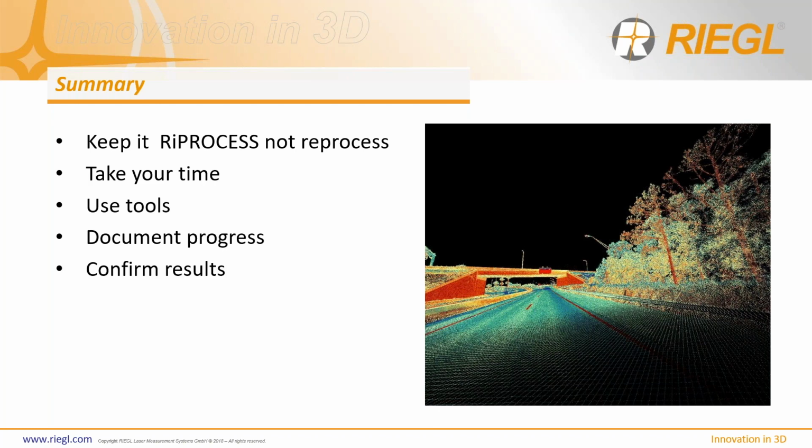Confirm your results. Check the control points. Check the data. Just because it says that it's supposed to be good in the RIEGL Precision report doesn't necessarily guarantee that it is. So check your results.